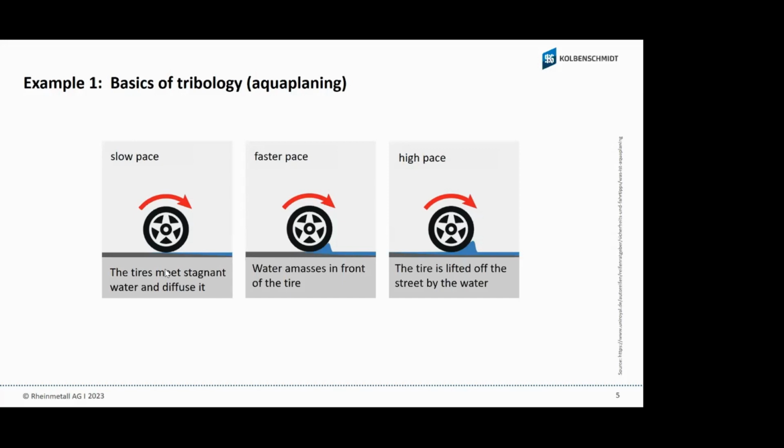When the piston speed goes up, the piston ring jumps up on this oil and moves on the oil film, like the wheel depending on the speed. This is also the situation when the piston is at top dead center. The piston stays for a microsecond, and when it stays and doesn't move, we go back to the first situation on the left side of this page.